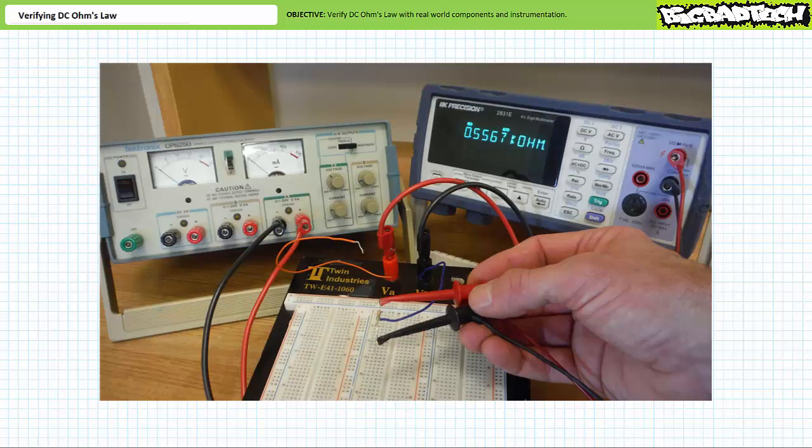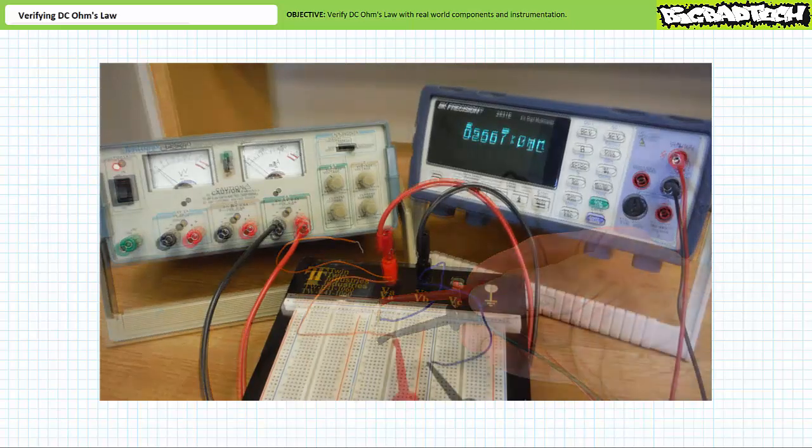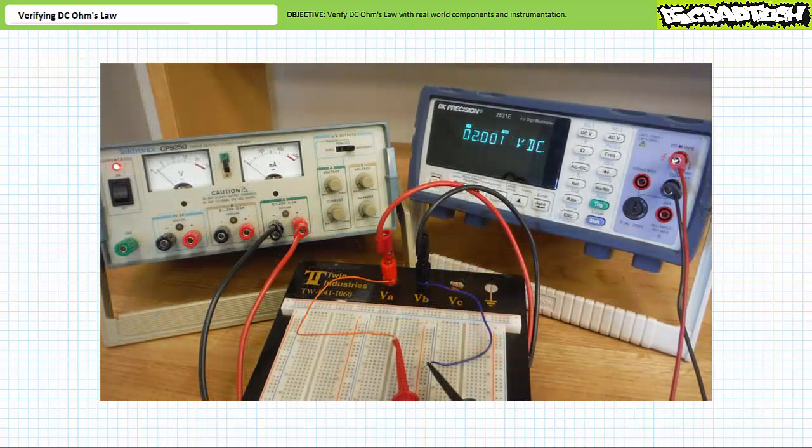This being said, given this resistor has a slightly smaller resistance than its nominal value, we might understandably expect our observed current to be slightly higher than our theoretical calculations might suggest. First, let's use a DC voltmeter to establish a 2-volt differential. This is the unloaded voltage, meaning it is the voltage established by the supply when it is not providing current to a circuit. We need to build the circuit and recheck voltage in the loaded condition to make sure it hasn't changed. Turn off the power supply.